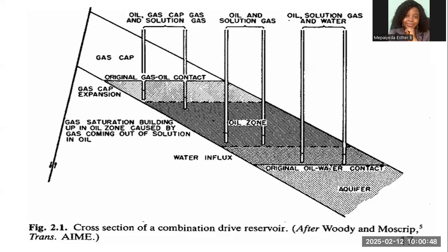That is the contact between your oil and your water. And here you have the contact between your gas and your oil. So here for these two wells, you can have the oil, gas cap gas and solution gas. You can have the drive from your oil, drive from the gas cap gas, and drive from the solution gas.